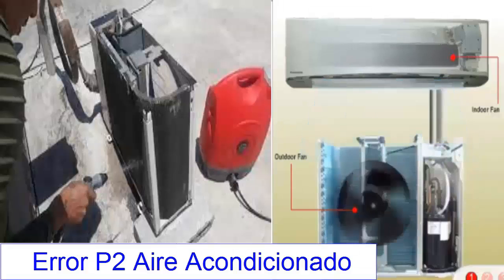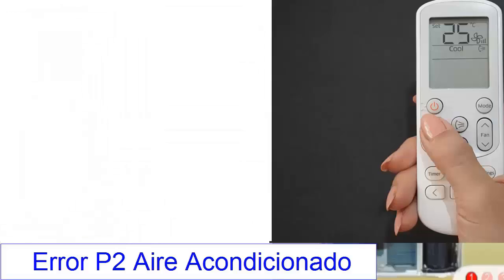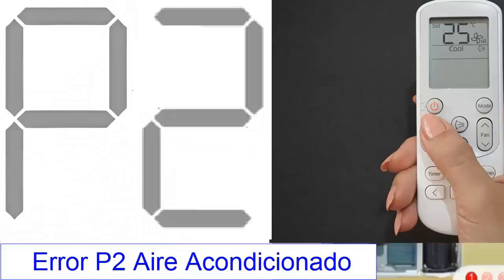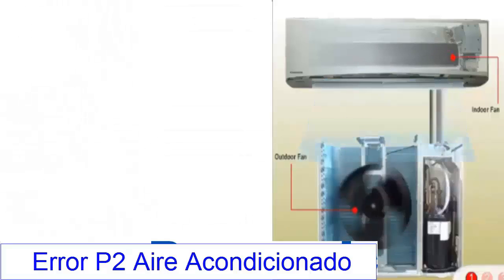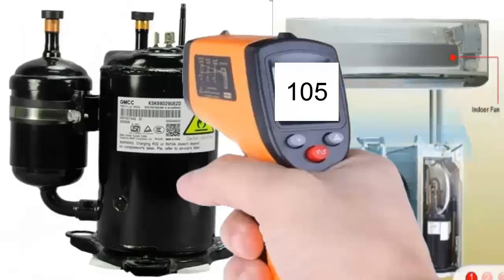5. Clean the air inlet and outlet or the heat exchanger of the indoor and outdoor units to ensure proper ventilation. 6. If the error persists, turn off the power and turn it back on after 10 minutes. 7. If the error persists, check the temperature at the top of the compressor. If the temperature exceeds 100 degrees Celsius, confirm a cooling error.